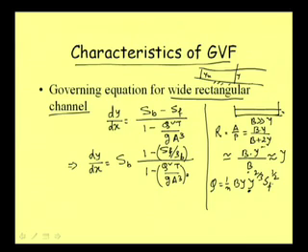If we remember, when we did the derivation for this resistance flow formula, this S value is basically SF. It is the friction slope. That is, we are basically interested in finding the slope of the hydraulic head line, that is, the total energy at one point upstream and the total energy at the downstream point. If we join them, we get a line that we call the energy line.